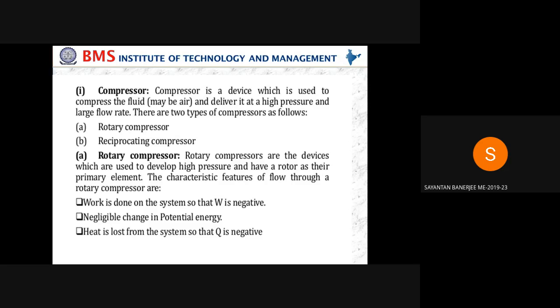So what kind of variation can you expect, approximately? Mainly pressure, velocity, and datum, position. Let us say at the mouth where the cross section is narrow, according to Bernoulli's principle, first I have calculated some values. So in real life, what kind of variation from those values will I see? Will I see a positive variation, in the sense, a value which is more than what I have calculated for air, or will I see values which are less than what I have calculated? That is a negative variation. For air, what do you expect?